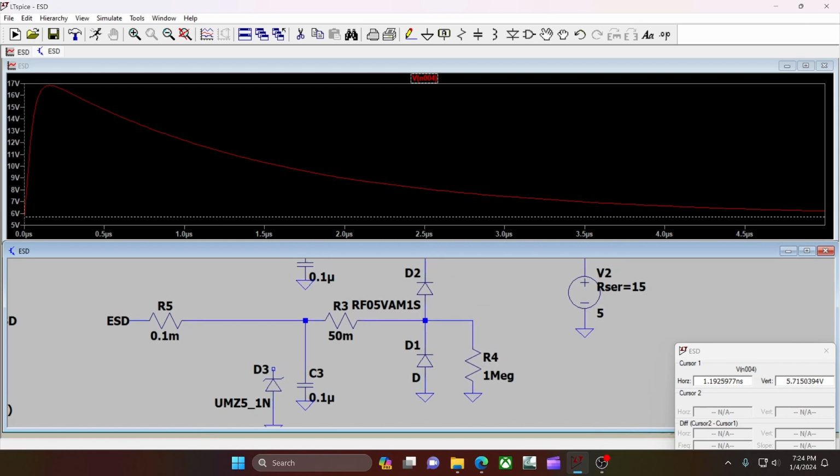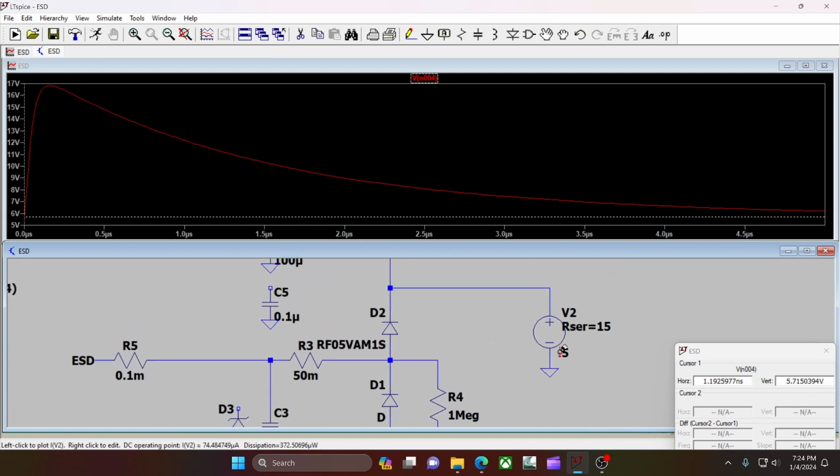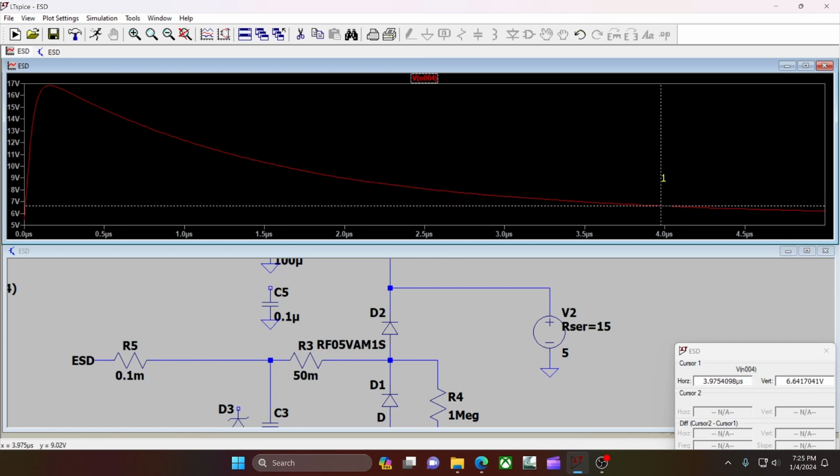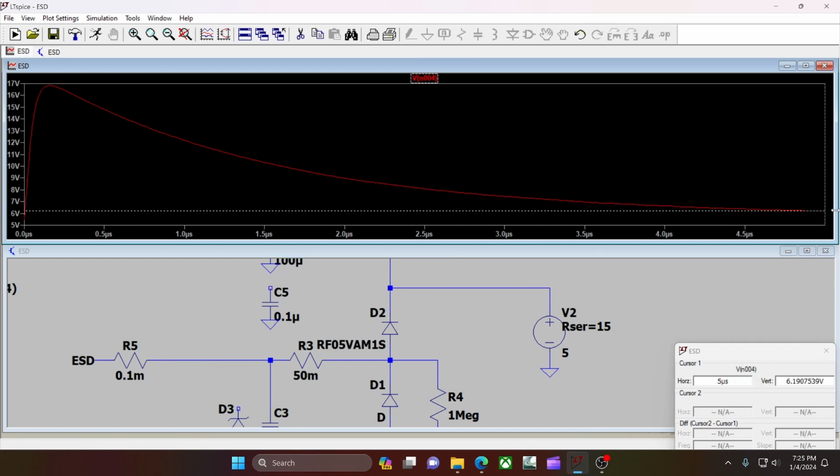So the question you might be asking, so I'm at 5 volts here. Usually the absolute maximum is somewhere around 5.5 volts. So is this okay? The answer is yes. For very short periods, like this will be fine. So do we get to 5.5? Just a little bit longer than this, we'd be at that 5.5 volts. So 5 microseconds, that ain't nothing.